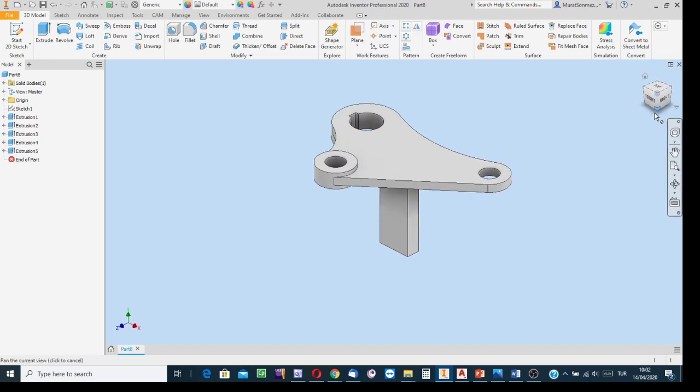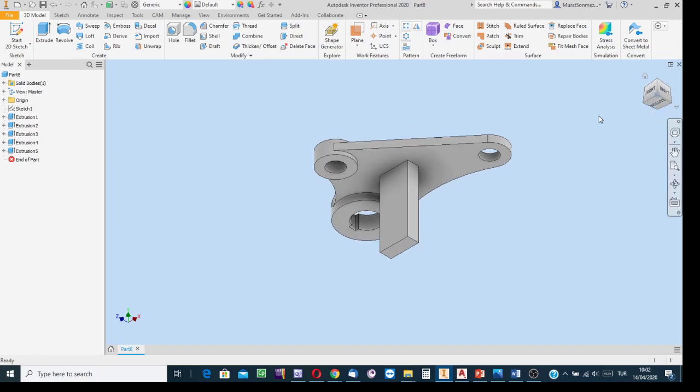And then, without forgetting, first delete the boss, which is this boss. It is at the wrong side. It corresponds at the browser to this icon. Okay, then see, if you created a feature by mistake, then you know how it is deleted. Find the icon that corresponds to that feature at the browser. While the cursor is on that icon, right click the mouse and select the delete option. Yes, I deleted that boss.